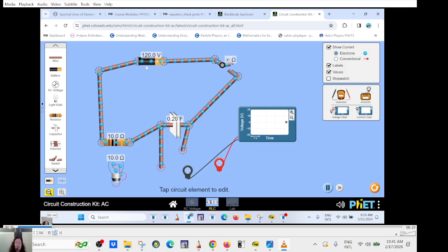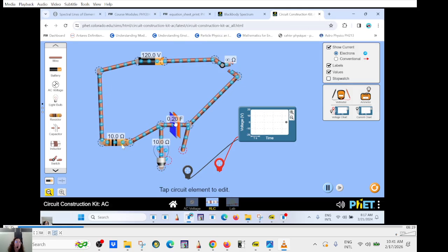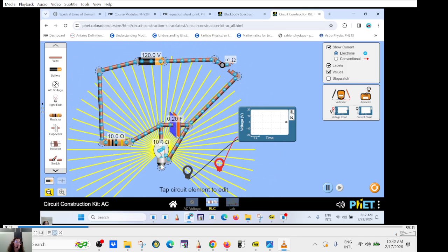Okay, so look here. I'm going to close the switch. Closing the switch. Look, very quickly, and then very slowly. Okay, and now the capacitor is charged. There is no more current. The voltage across here will be 120 volt, and I can discharge it in a load.